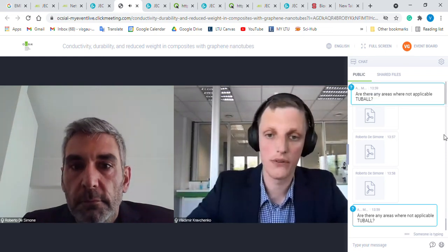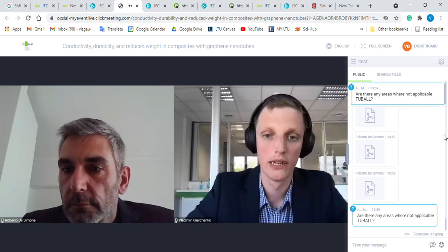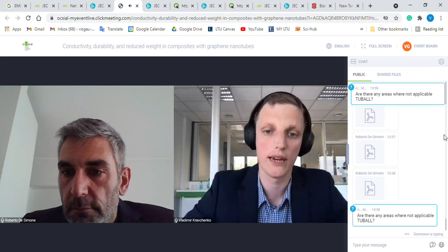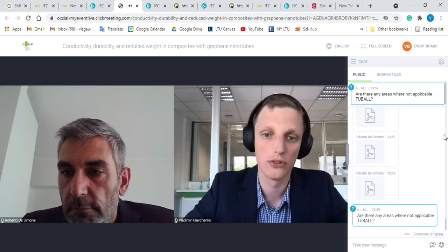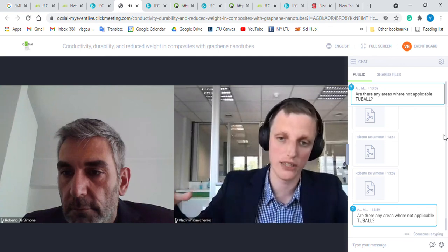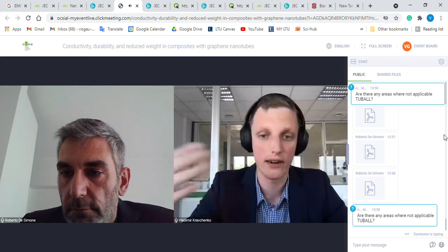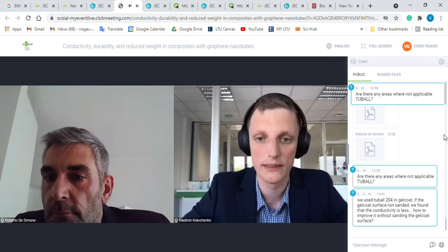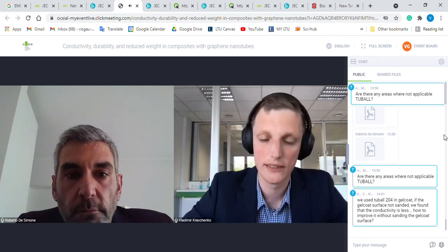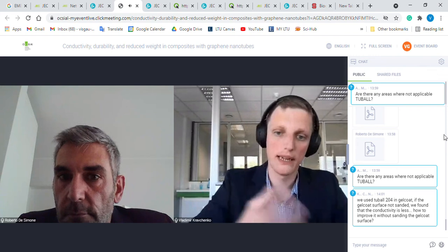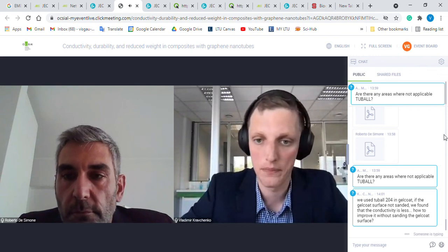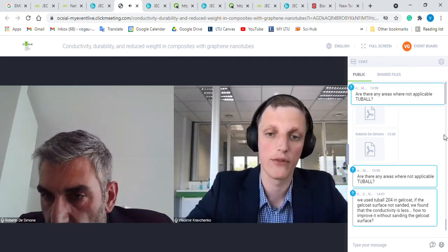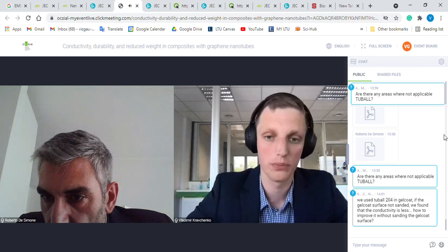But for vacuum infusion or resin transfer molding, currently we do not promote or propose any products, because nanotubes have limitations of viscosity and also filtration during big-scale production. So at the current development stage, this is one example. It's a universal additive, but of course a technical tool with pluses and minuses, and we are trying to define which applications have been validated from both technical and commercial points of view.